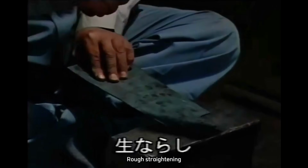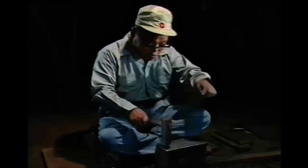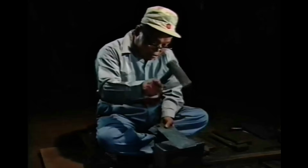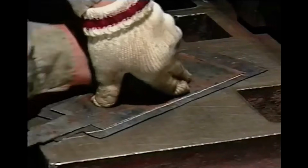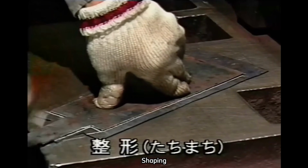Annealing involves heating the steel once in the furnace and then waiting for it to cool. By hammering the cooled steel, surface irregularities and twists are flattened out, and the steel is compacted by the hammering. It is scribed to the required dimensions and cut.